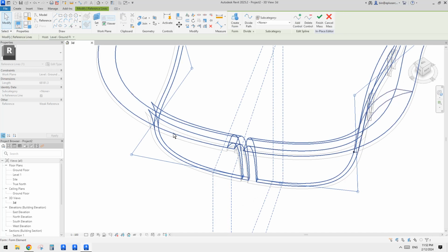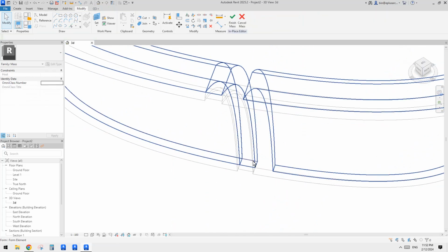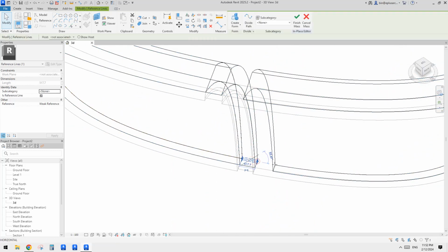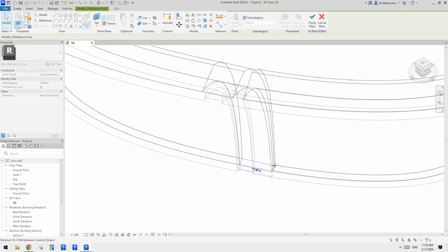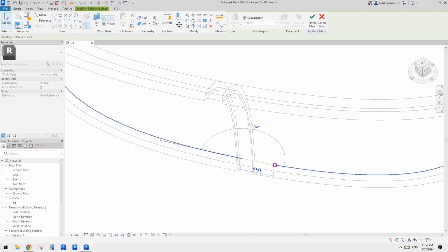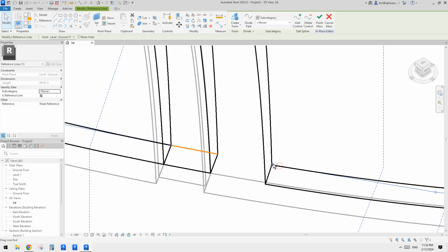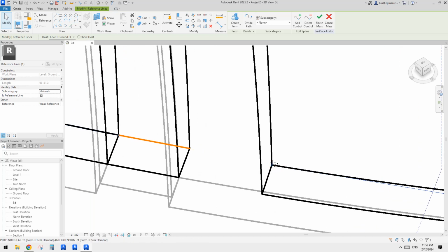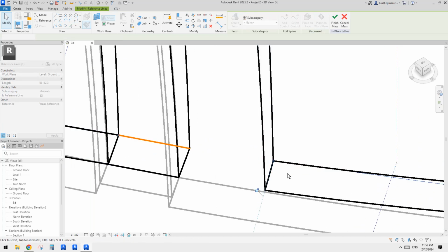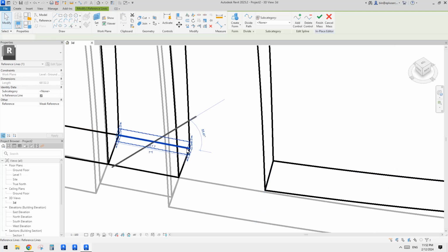It won't affect the rest of the points on that spline. So okay, now I just need to drag this back, maybe type SE to snap, and looks like it will break this one. That's fine. So maybe I'll just adjust this a little bit, go up a little bit.